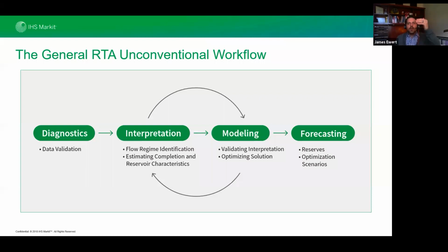Spending time looking at the quality of your data before you move forward has to be done every time. People don't do it because they want to save themselves a little bit of time, but I've seen a few cases in particular where it's cost them a whole lot of money. So data diagnostics, you're going to do that no matter what well it is. You're going to look at the raw data, the ratios, you're going to get a sense if there's any gaps, you're going to look at the pressures. You just want to get a sense if everything looks sensical, if there's a natural, nice flow to the information.